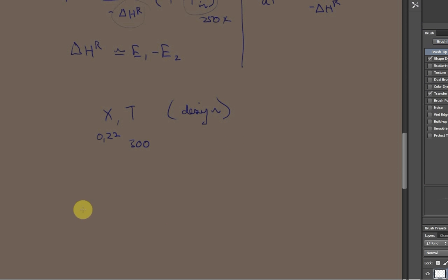Well, let's do it. So we've got V equals FA in XA, and we've got RA, and RA is K1 CA, and we know CA is CA naught (1 minus X), minus K2 CB. So CB is CA naught X. We're using XA here, so we should say XA and XA.